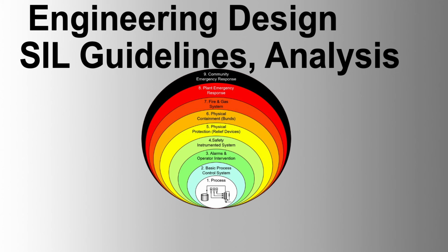6. Documentation of FTA results. Document the SIS application, assumptions, reference documents, data, model, cut sets, PFD, MTTF spurious, sensitivity studies, and recommendations for SIS improvement. This procedure ensures a comprehensive evaluation of the SIS, helping to identify weaknesses and improve system design to achieve the required SIL. The documentation provides a detailed record of the analysis, supporting ongoing safety and reliability efforts.